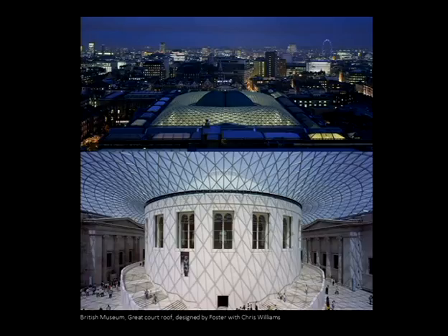But what we mainly talk about in the lecture on grid shells and shells is steel in this very lightweight form, like in the Great Court of the British Museum. Here we have more than 1,000 different pieces which are bolted and welded together, partly off-site and partly on-site, but the form of this roof is done in such a way that, again, there is only membrane action. So this is a shell.